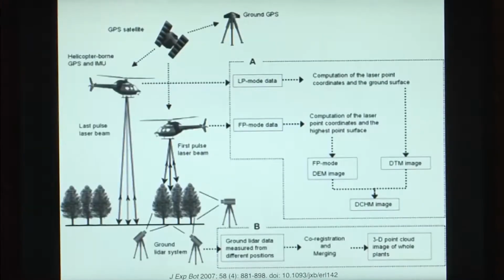So, this is how this scanning would look like. We could go for ground based scanning, which would be called a ground LIDAR system. We could put it on an aircraft, say an aeroplane or a helicopter. We could even put it on a satellite, or you could put it anywhere essentially, but you need to know your position, you need to know all the angles, and you need to calculate the time of flight of the